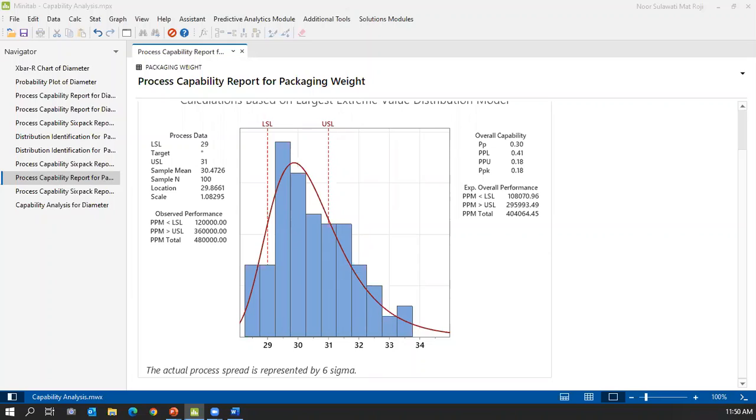You look at whether your measurement is good or not good for measuring your parameter before you go further, like stability, and then capability. That is the theory part. But I think most of us look at the CPK first, then go back to the control chart, and after that go back to the measurement system analysis. But in the theoretical part, the best way is to start with the MSA.